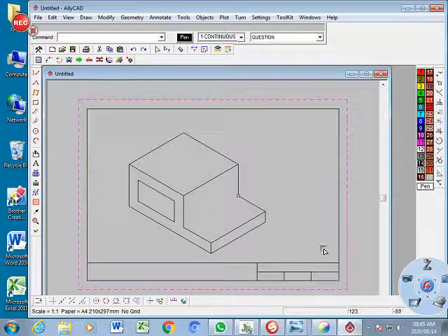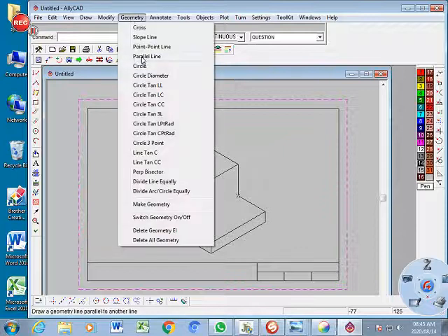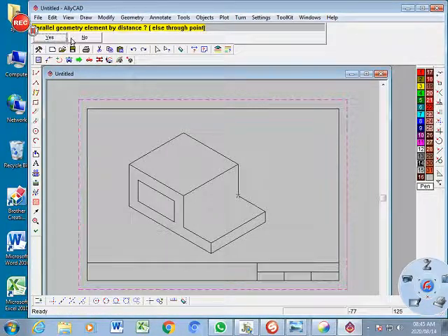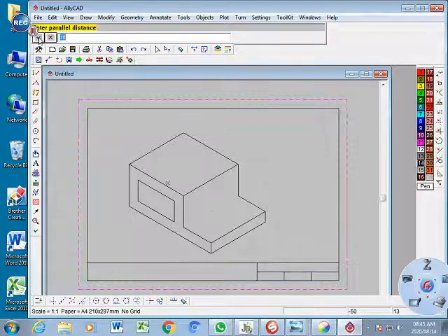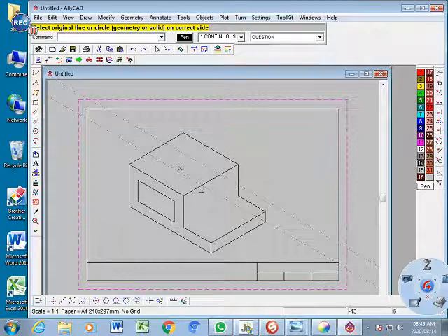Okay, now what I'm going to do is, you know that there's going to be a corner, but don't worry about that, we're going to put it in a moment. So I'm now going to say I want 20s here, so I'm going to go parallel, yes, and I'm going to say yes, and I'm going to measure off, say 20s here. Click next to that line, and I'm going to say 20, click yes, and another 20, yes. There I've got those corners here.